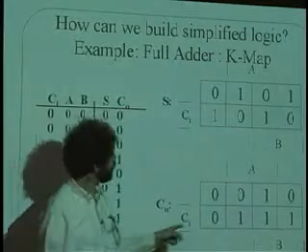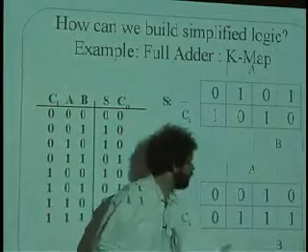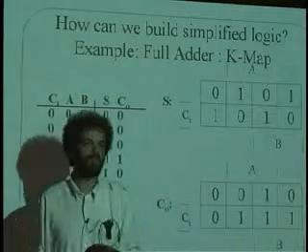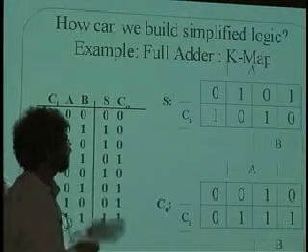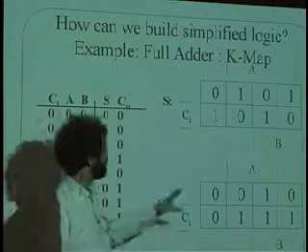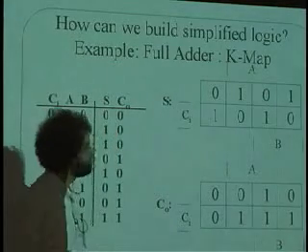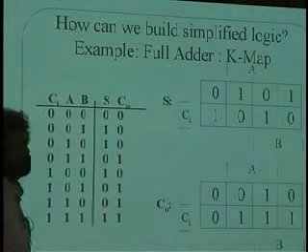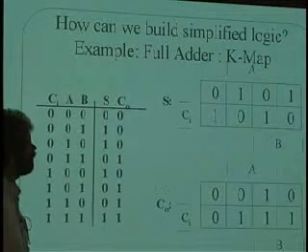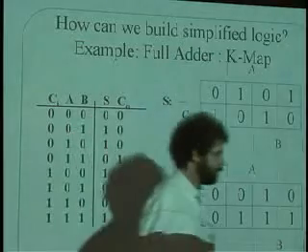And in fact, the way that the bits change as you go around and around here, and you may have learned this, is called a gray code. Only one bit will change at a time. And so this has the characteristic that the axes are labeled in gray code. It's a fantastic device for simplifying logic expressions.